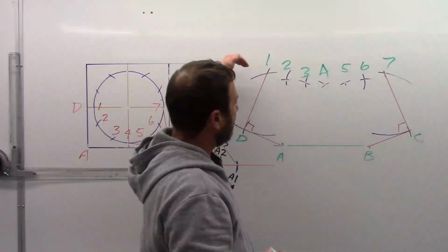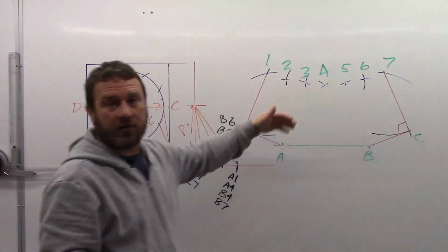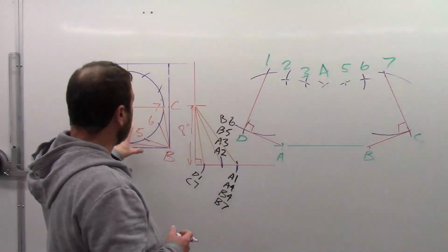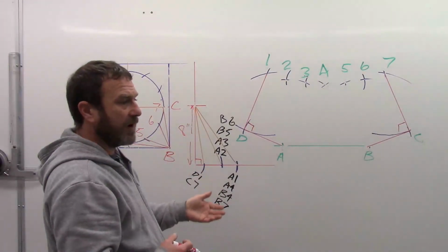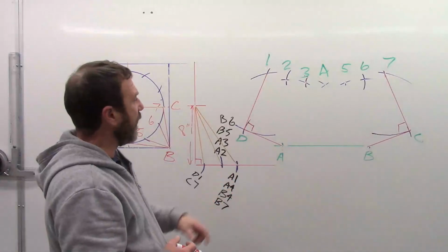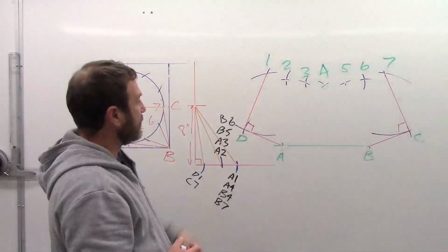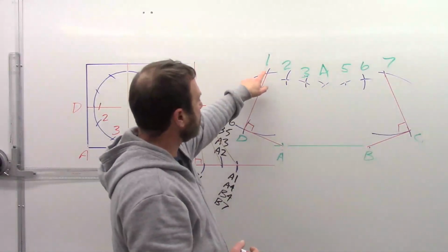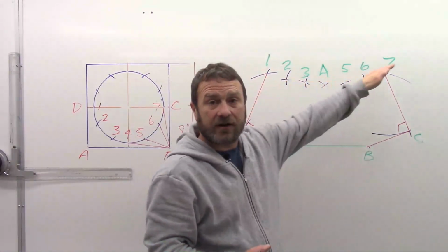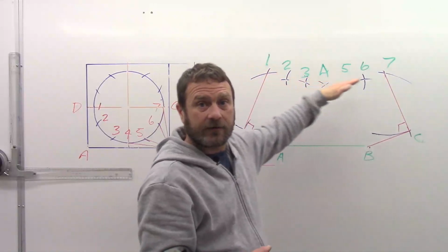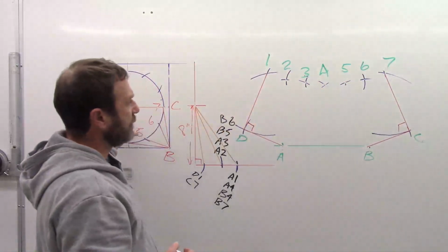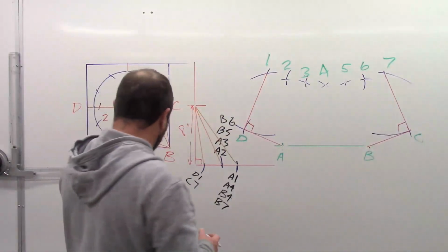Okay, and because we're using step-offs, and we've talked about the inaccuracy of using step-offs, you can calculate out mathematically your 1/12 and actually get a straight line and use that as your step-off. You can also take a piece of string or something to measure this, okay, at the end. And if we measure it, it should equal a half circumference. So we can check that mathematically as well.